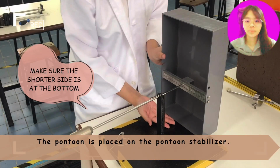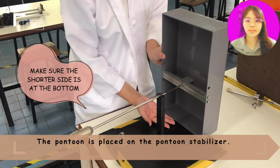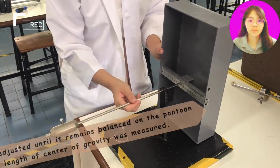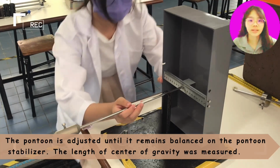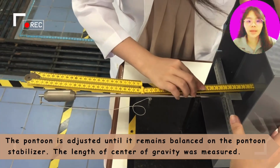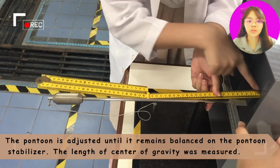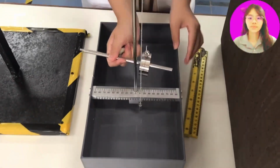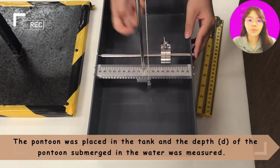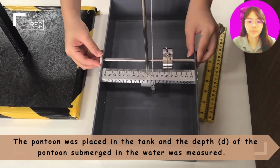Then place the pontoon on the pontoon stabilizer and make sure the shorter side is at the bottom. Next, the pontoon is adjusted accordingly until it balances on the pontoon stabilizer, and the length of the center of gravity was measured from the base of the pontoon to the middle of the beam. The horizontal weight was fixed and the position of the thread is set at 0 mm.